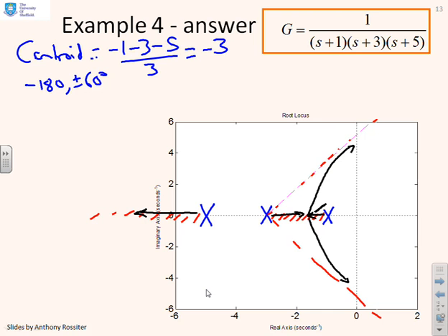So I'm going to guess that this intercept point is approximately -1.8. Now that is a guess. You can calculate them exactly from breakaway point analysis, but it's quite numerically intensive, and it's really not worth the effort. If you really wanted that value, go to MATLAB. So I'm just guessing it's about -1.8. So that will make the slowest poles real and equal.